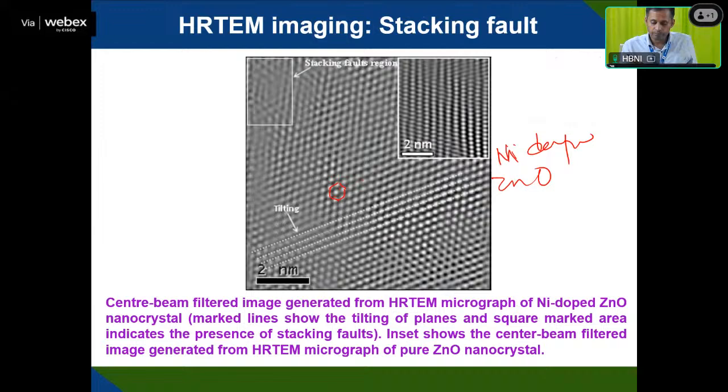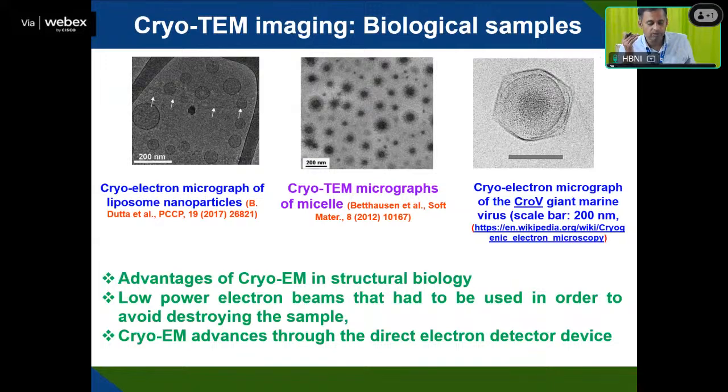And then if you go for a better inverse Fourier transform, you can see the wavy nature because of the stacking fault, the dislocation. In addition to dislocation, there is some slight displacement of atoms, how it's happening instead of going straight. So this bend is here. So that information you can see here. The plane is coming here. This plane should be arranged like this, but later on it deviates from the main line, and the atoms are arranged like this. So there is a deviation. This deviation is called stacking fault. So that metallurgical information we are able to see.